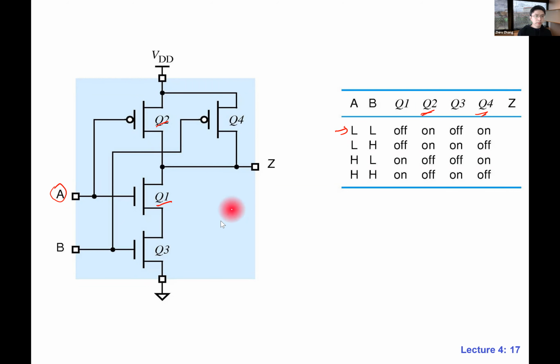But let's look over here. This is the NMOS. This is something that we'll see pretty often later on: this duality. When we have a parallel structure in PMOS, we have something called the series structure in NMOS. These two are put in series, so they are stacked together.